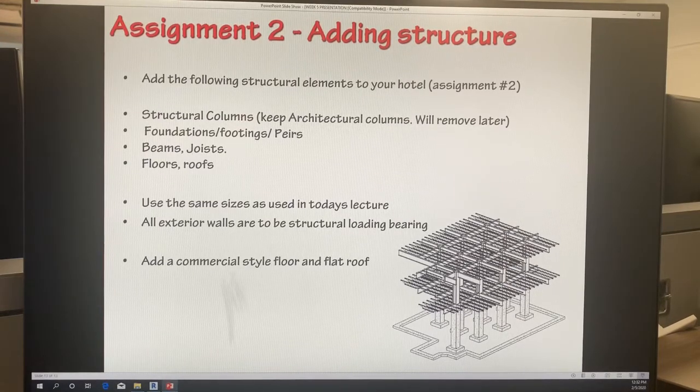Any questions? Sorry? Yeah, you do the beams on the first floor and then paste them up to the roof level. But you may want to do the paste before you drop your beams down, because the ones at the top should not be dropped.